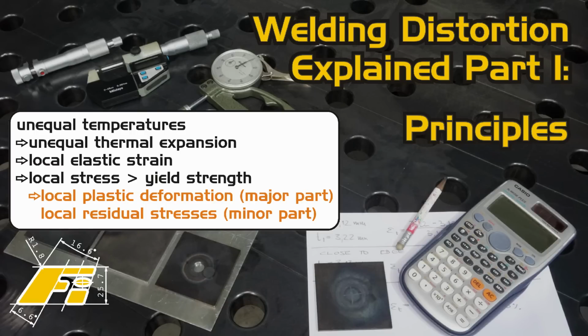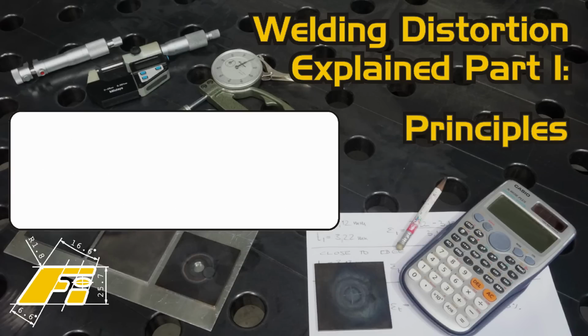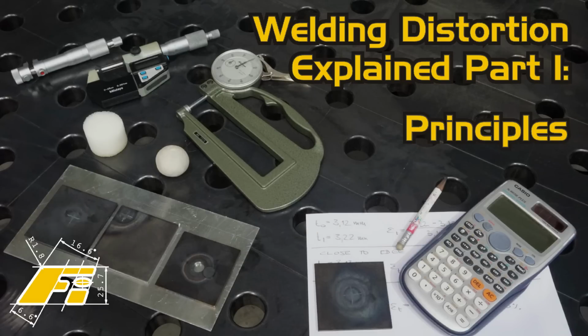They add to the stresses which the component encounters due to operation. Consequently, they may reduce the strength of the component. That is why in the practical world, in most cases such welded components are oversized and strictly required to possess pronounced material ductility and toughness. The latter potentially allow for reduction of high residual stresses in case of the first maximum load or overload.